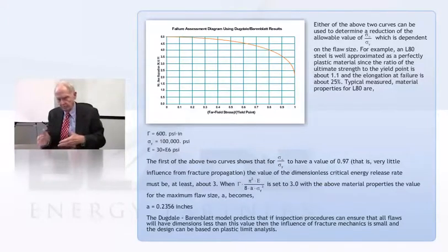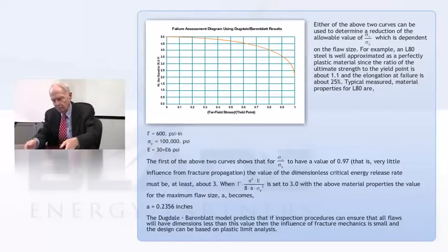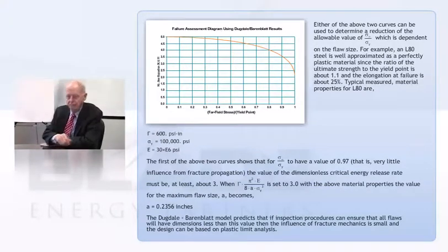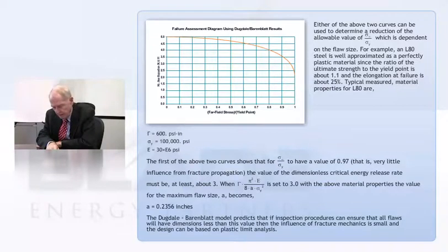but in every case I've ever seen, for the scheme that they use for materials, steels used in the oil industry, the yield point always is much greater. See, this is guaranteed to be 80 KSI, and you can see when you go to measure it, you get closer to 100 KSI. And these are numbers taken off of averages for a lot of different samples. And then this gamma, which had to be measured. And I have to say a few words about that because this is not an easy number to get. It involves some pretty tricky technique, and it's very expensive. So these numbers are just not everywhere. And then Young's modulus, of course, is 30.